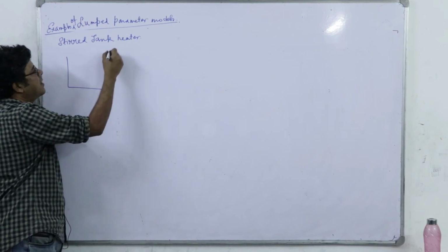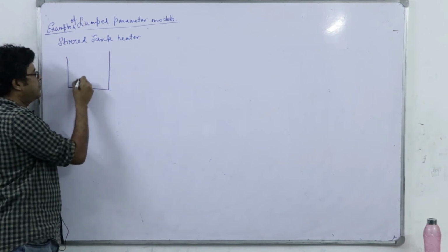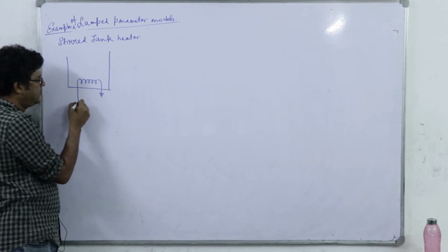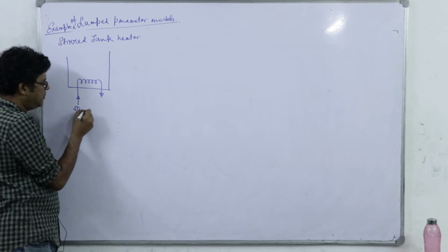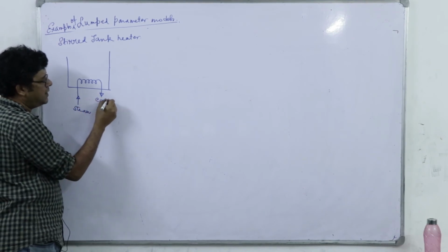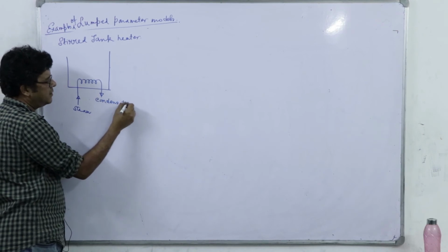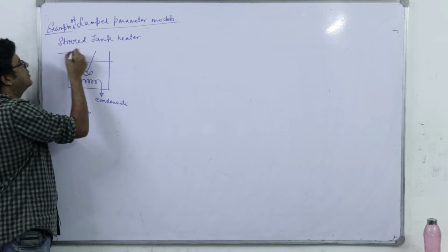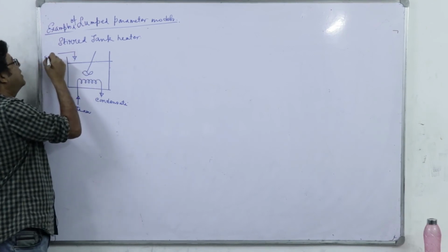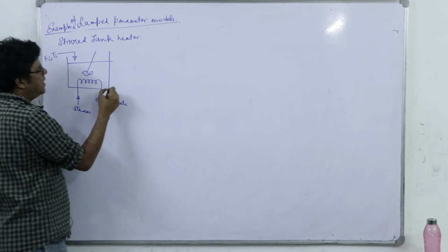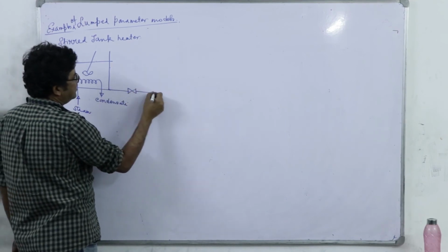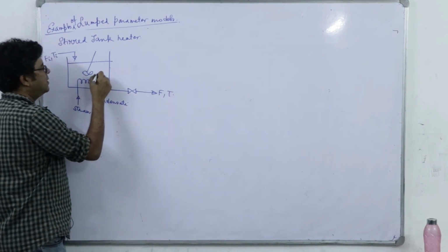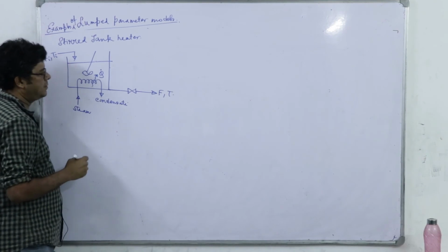So what is that? It is a steam coil where we have steam, and it is only exchanging latent heat, producing condensate, and there is a stirrer. We have inflow Fi with inflow temperature Ti, outflow F with temperature T, and the heat flow rate is Q dot, right.